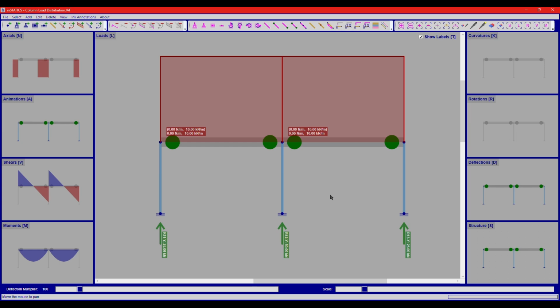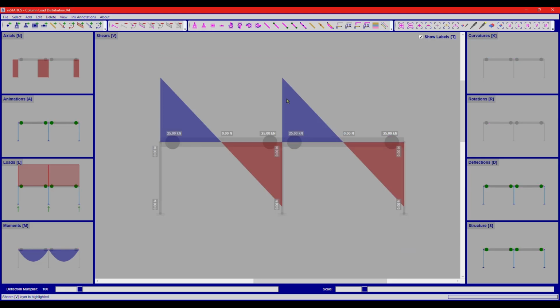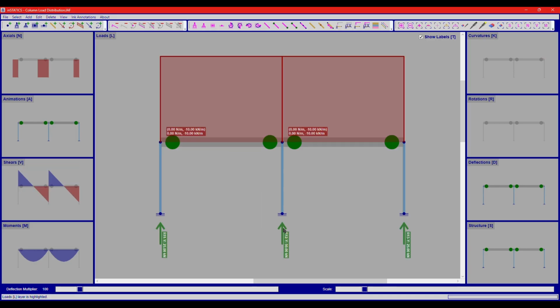It is common to predict preliminary gravity loads on columns based on tributary length. In structures with simply supported spans, half the load flows to each side. If we have an inside column, we add the loads coming from both sides. This means for relatively ordinary structures, inside columns carry twice the load.